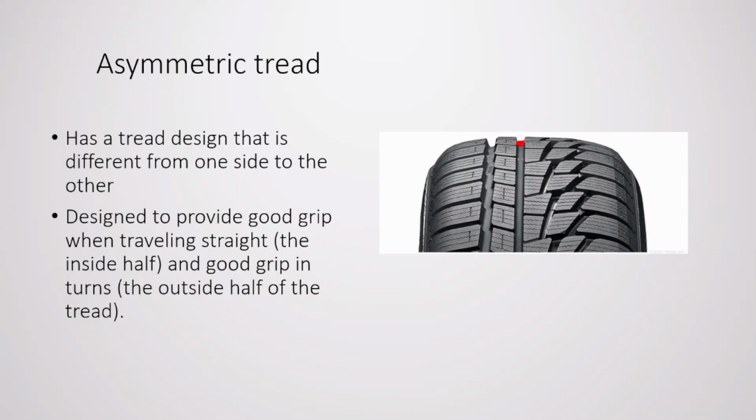Once we reach this level, we need to replace the tire, but it is not very common in the Sri Lankan context. We drive with the same tire until we see no tread pattern there, right? That is not recommended. Once we see the tire wear indicator leveling up with the available tread height, the tire should be replaced with a new one, right?